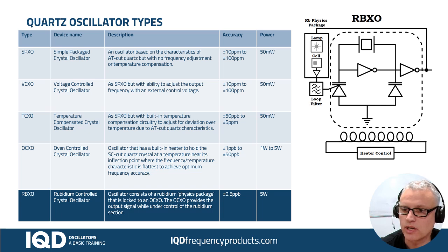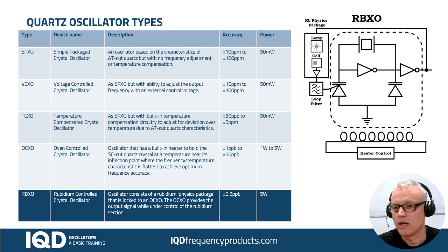As the OCXO begins to drift over a few weeks, we might see fewer photons received on the cell. With fewer photons received, we know something's wrong, so we have a system here that pushes the frequency of the OCXO to build it back up again to correct for that, and so we have a feedback loop that's pushing the frequency of the OCXO as determined by the rubidium gas here.